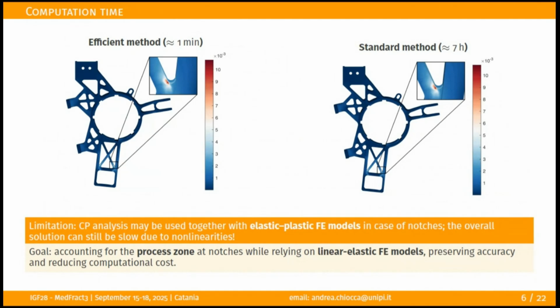So these are notch components under multi-axial non-proportional loading. This is a map of Fatemi-Socie. The maps are the same, but with the method we implemented they are different. Here it's just 1 minute of computation. Here are some hours of computation to find all the critical planes.